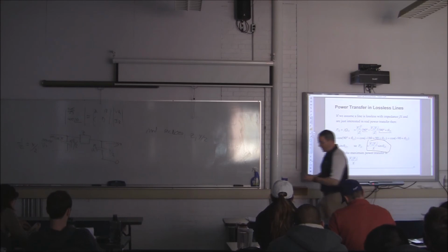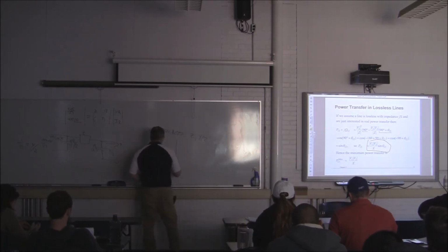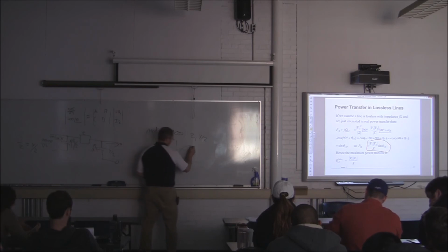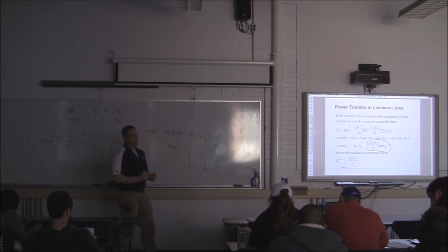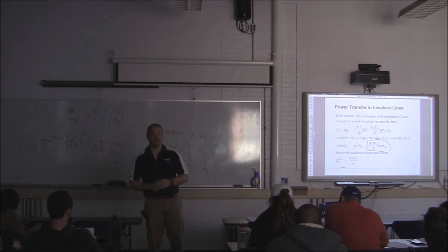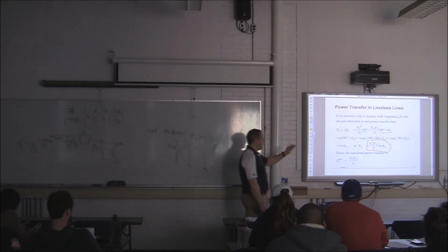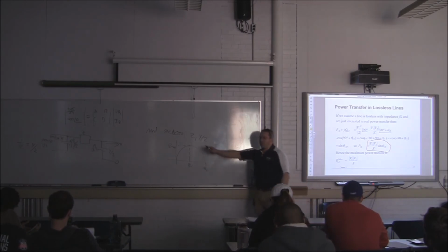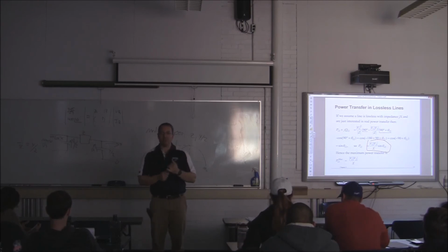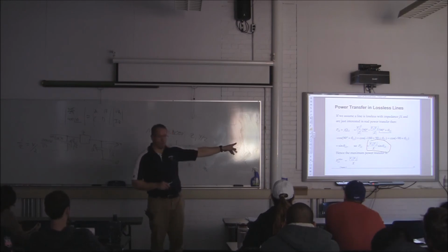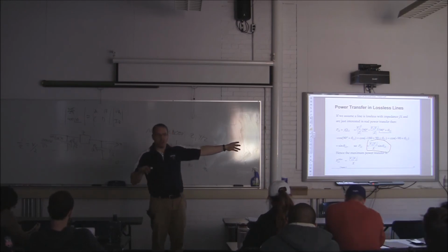So if you look at a transmission line, your power flow typically follows something like this. 90 degrees, 180 degrees. This is P max. That's the maximum capability based on the voltages, regardless of, hey, is this exceeding the capability of the line? This is max what I can do based on those voltages. So remember how we said, look at the angle? What's the biggest predictor of how much power flows in a line? Well, you can see the magnitude of the voltages have some influence, but again, those aren't going to vary more than plus or minus 5%.